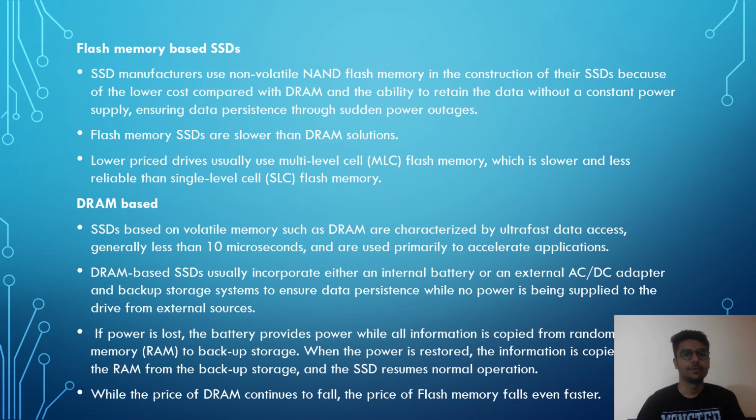First of all, flash memory based SSDs. SSD manufacturers use non-volatile NAND flash memory in the construction of SSDs because of the lower cost compared with DRAM and the ability to retain the data without a constant power supply, ensuring data persistence through sudden power outages. Flash memory SSDs are slower than the DRAM solutions. Lower priced drives usually use multi-level cell flash memory, which is slower and less reliable than single-level cell flash memory.